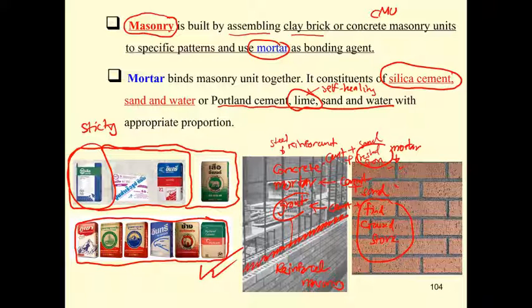And when night comes, the temperature drops, and that rain will turn into ice. When water changes status from water to ice, it expands. Expansion may cause cracks in the mortar, and when the ice melts to water, it can react with the chemical in lime, and that chemical can seal the crack.